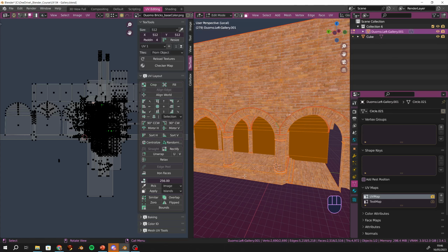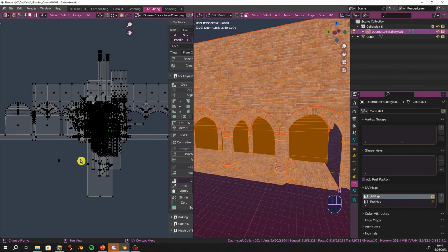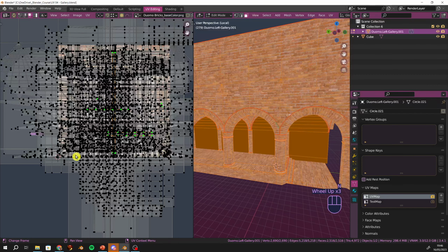You cannot use a UV map which overlaps or doesn't fall into the texture space if you're baking. Correct. It can't overlap. It can't be outside the grid. So you've got your 1024 by 1024 brick texture in Second Life, and because you've mapped it out, when you take it in, it'll know how to scale that texture onto those faces. Yes, it will show exactly like this, but nothing is baked in it, and that's when you start baking. That's why you need a second UV map. Then you can translate one into the other, and the second one is for baking. That will fall in the texture space and won't overlap. That way you can bake in shadows and stuff.